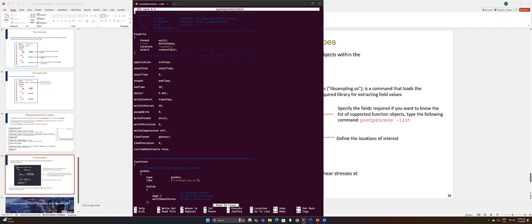Don't mind what is down there for now. You can see that our application is icoFoam here. So that's what we'll be using. We are starting from time 0, the start time, and ending at 20. But I think 20 is a bit too long.